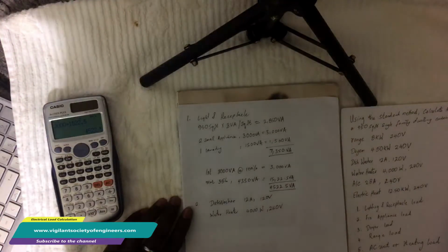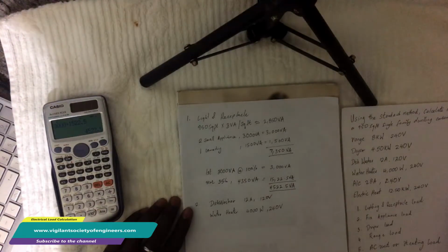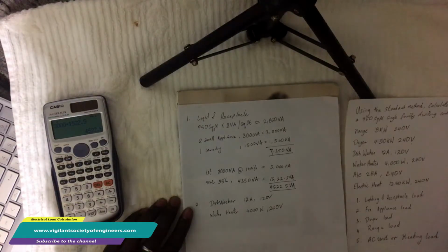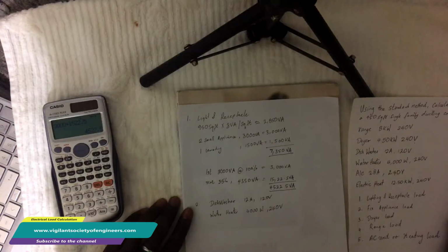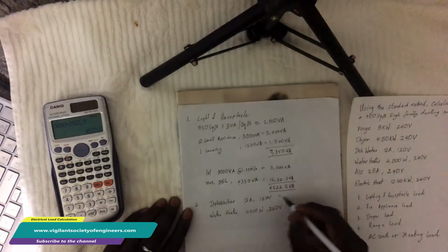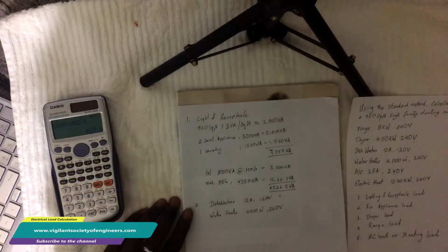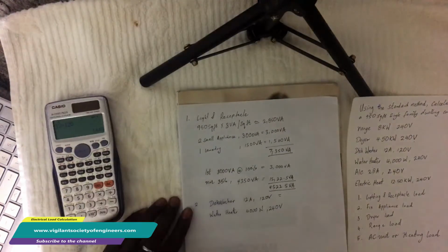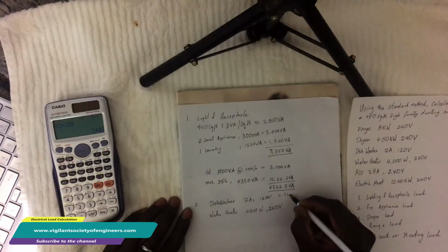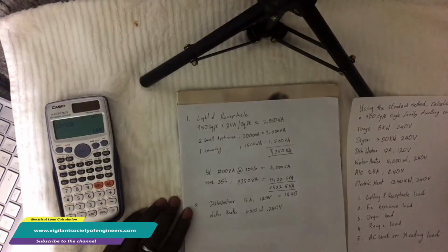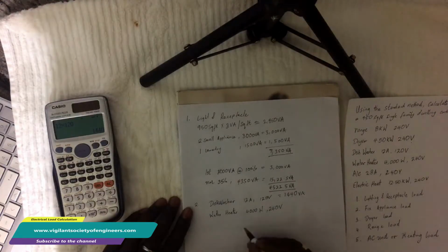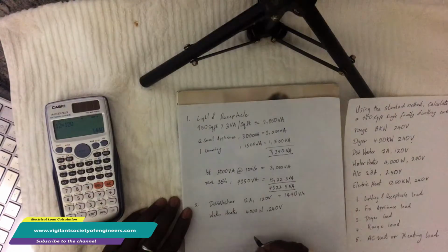All right. So for the rules regarding fixed appliance unit, when we have 4 or more appliances, we will take 75% of that load. In this case, we have less than 4, so we will take 100%. So let's find the value for the dishwasher. That is 1,440 VA. All right. So all we have to do here, just add both values.